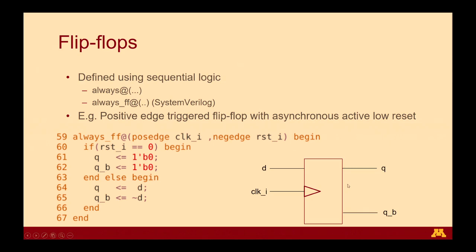Is there a data flow model for a flip-flop? You need to actually keep it within an always block, because in this particular case the non-blocking operator will only work in the always block. It will not work in an assign statement.